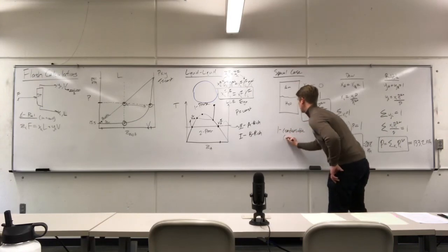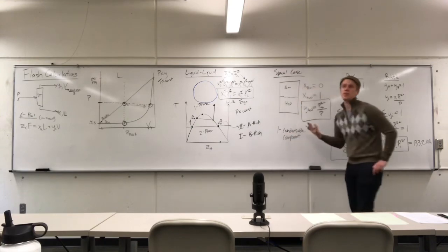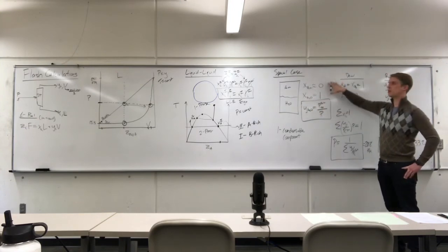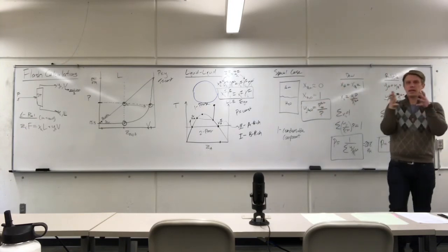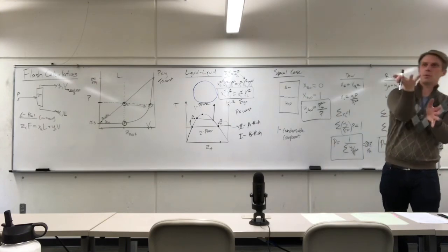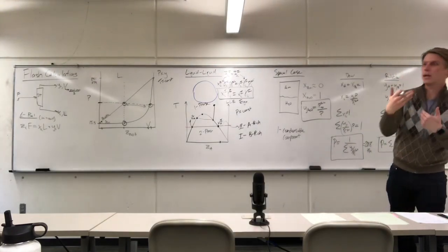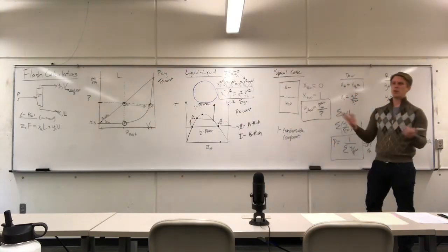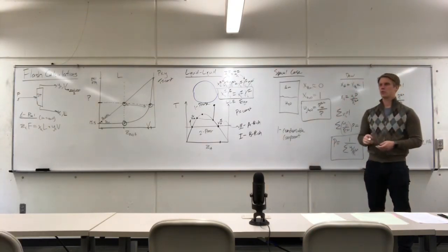It's a simplification. This doesn't have to be water, it could be any fluid, but the approximation holds true. If I have a condensable fluid with a supercritical fluid, which is the case of water and air, I can assume that the air is not appreciably going to dissolve. I mean, it will, but we're talking like 10 to the minus 4 mole fraction, 10 to the minus 5 mole fraction. Not something that's ever going to significantly impact your calculations.